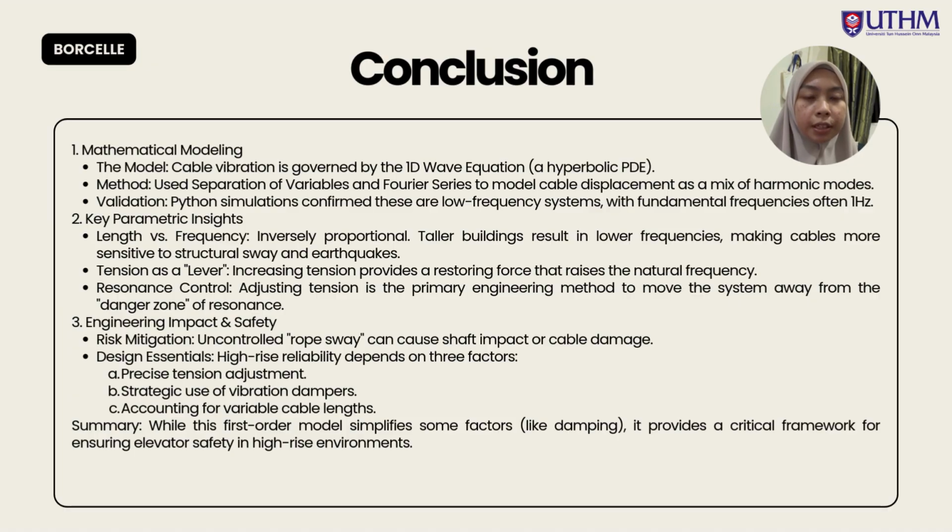For the safety and final recommendation, why does this matter for real world safety? If we don't control this vibration, we risk rope sway. This is not just a comfort issue. It can lead to the cable hitting the elevator shaft or damaging the steel strand, which is catastrophic.